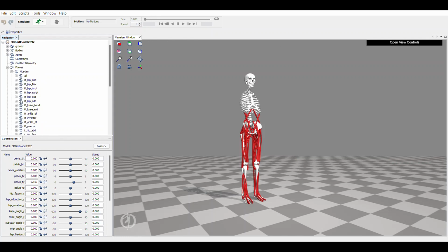So you can even list a group of muscles. For example, if I take up the right knee extension, rectus femoris, vastus intermedius, lateralis and medialis muscles have been listed inside the right hand side. So, the right reference point, right hand side knee extension. In that group you can see all four muscles. So over here we control the muscles, I mean, which muscles we need to view, and we can change the properties of the muscles. Everything will be done in the navigator.